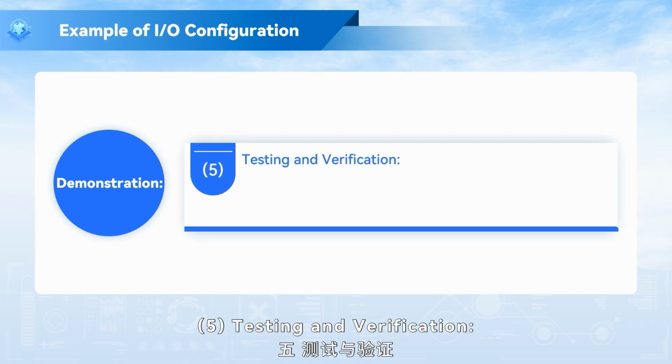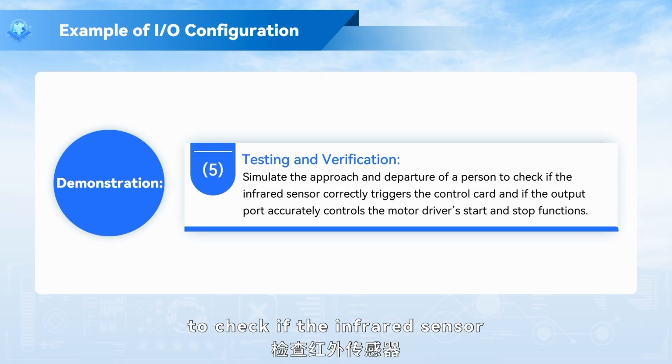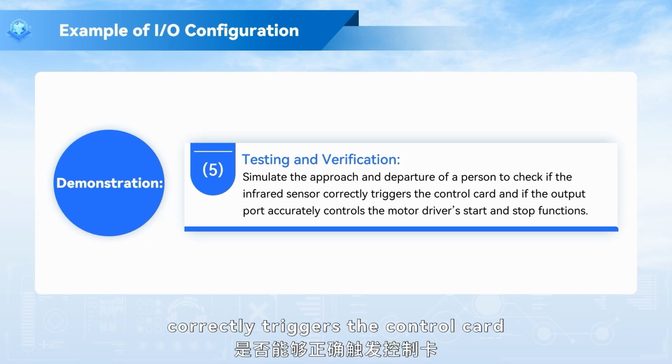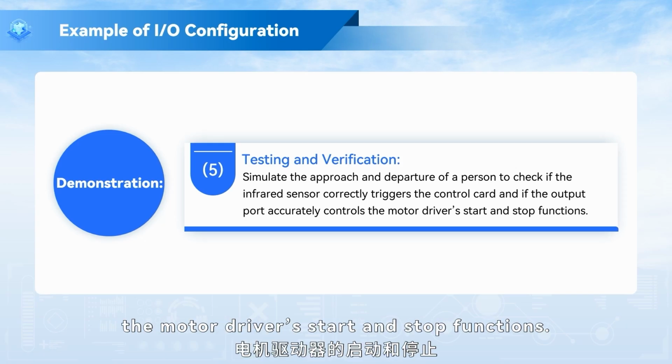5. Testing and verification. Simulate the approach and departure of a person to check if the infrared sensor correctly triggers the control card and if the output port accurately controls the motor driver's start and stop functions.